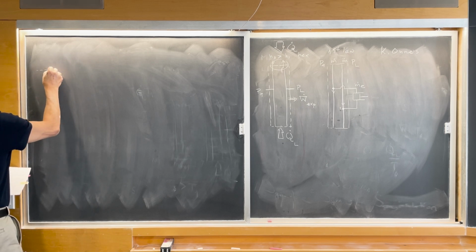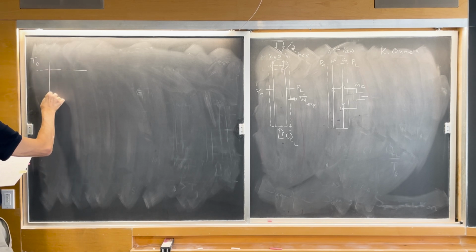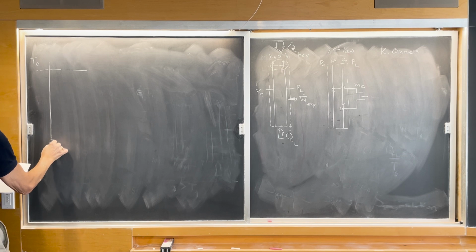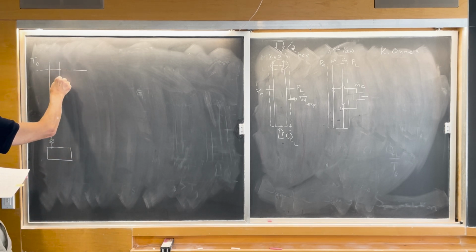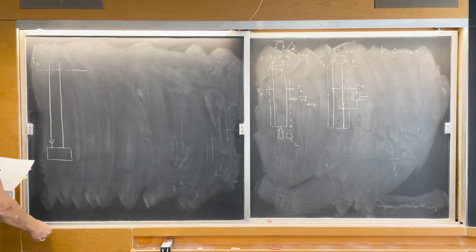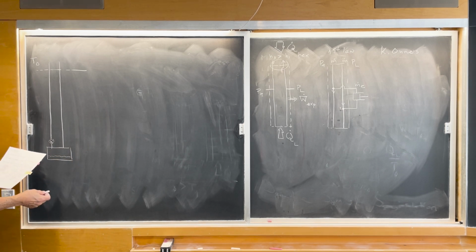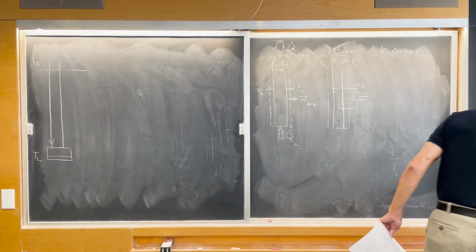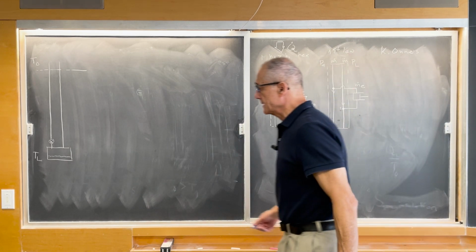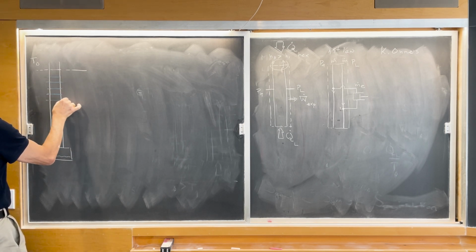So we have the ambient here, and then the two streams in counterflow. This would be the throttle. We're not concerned with the evaporator. We're simply concerned with the counterflow that connects room temperature with low temperature. And imagine that those two streams are in very good thermal contact side to side. That's the meaning of counterflow heat exchanger.